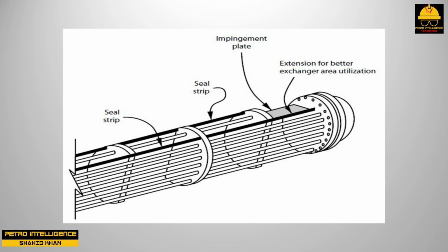However, when I said that the seal strips needed to be as long as the tubes, that is not quite right. One of the pairs of seal strips must have one strip that stops at the first tube support baffle. If not, the shell side feed would be trapped above the impingement plate. If we have vertically cut the tube support baffles, then the seal strip that is aligned with the edge of the first shell side tube support baffle should extend to the tube sheet.